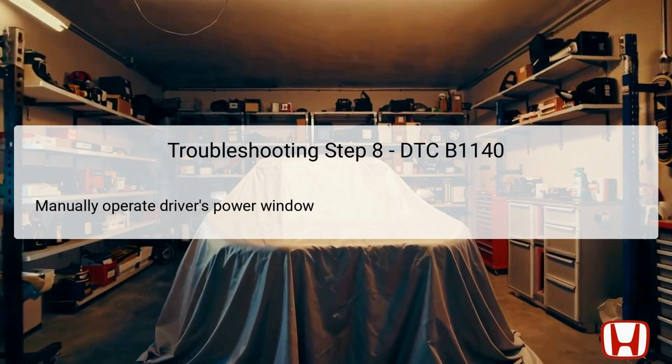This step is crucial as it helps to determine if the substitution of the master switch resolved the issue associated with DTC B1140. If the window operates normally, it indicates that the original master switch was faulty and has been effectively replaced.